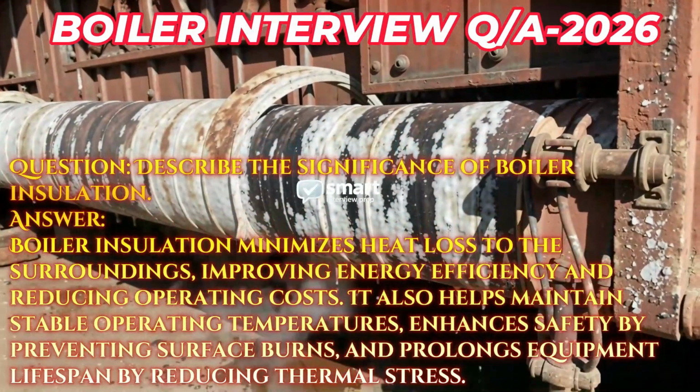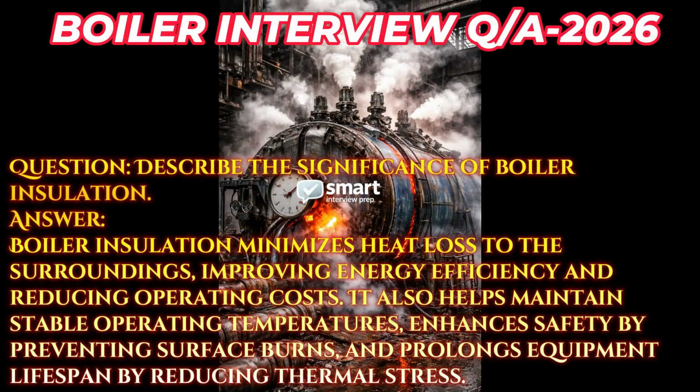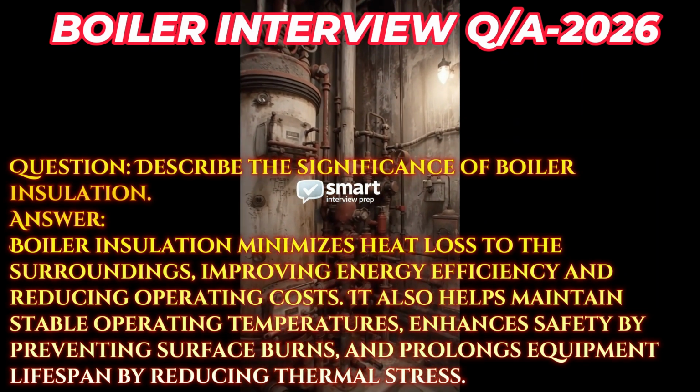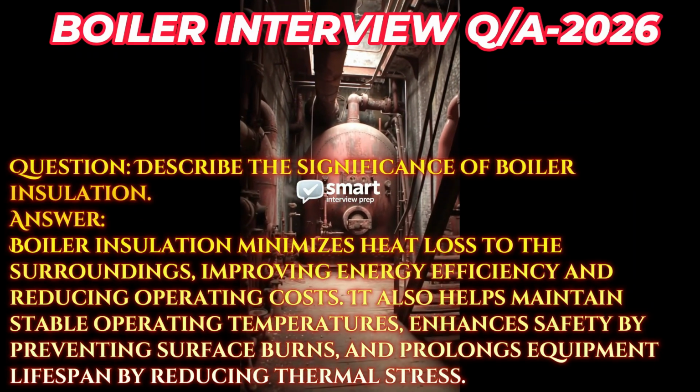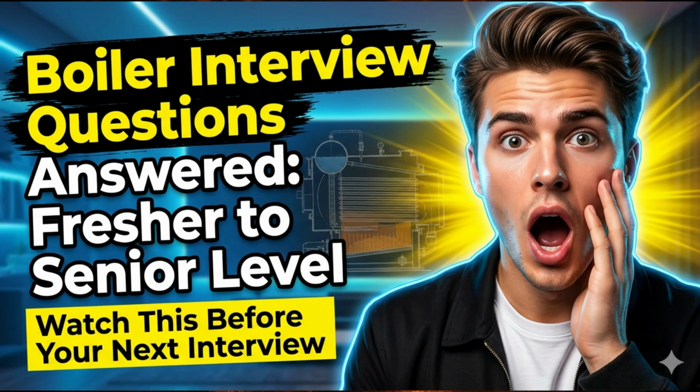Answer. Boiler insulation minimizes heat loss to the surroundings, improving energy efficiency and reducing operating costs. It also helps maintain stable operating temperatures, enhances safety by preventing surface burns, and prolongs equipment lifespan by reducing thermal stress.